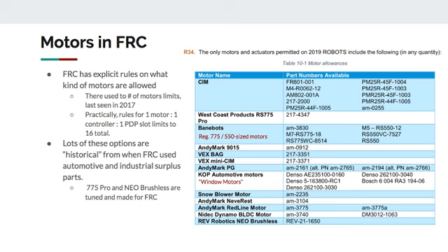So the window motors were motors that you could use. I should have put a picture of a window motor in, but it was basically a smaller motor, maybe a 300 or 400 size, so about half the size of the 775. The nice part is that this was before the VersaPlanetary gearbox existed. So the window motor was already connected to a worm-style gearbox that turned the output 90 degrees and already had something like a 100-to-1 ratio, so it was very useful as we go through the later parts.